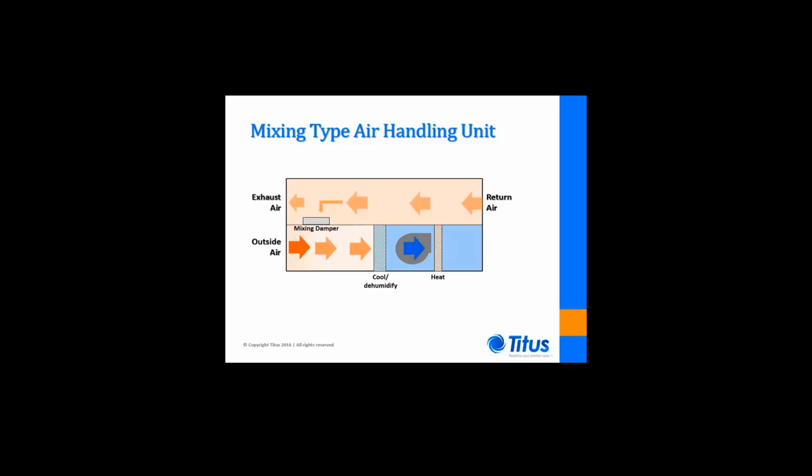It is then reheated to bring it to the desired discharge temperature before delivery into the classroom. An effective way of providing the necessary reheat is to provide a heat pipe or runaround coil to transfer heat from the air mixture before it is cooled and dehumidified to reheat the air leaving the coil.